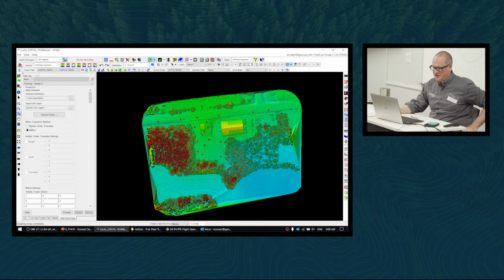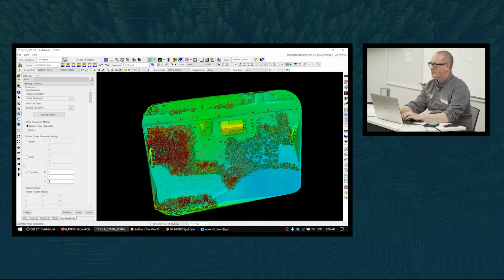We'll keep it simple for this one right now, but we will be using these point cloud tasks all day. Let's click on rotate, scale, and transform, then click on translate, and on the Z value, we want to put in that mean error that we had. So I'm putting in negative 0.048. What was that under translate, and you went under the Z? Mm-hmm. Yeah, correct.